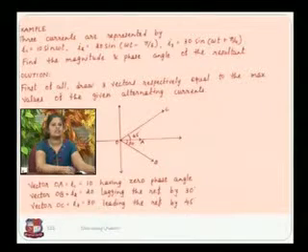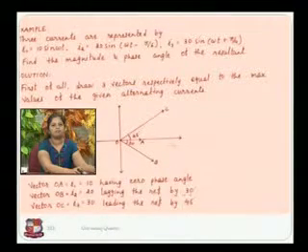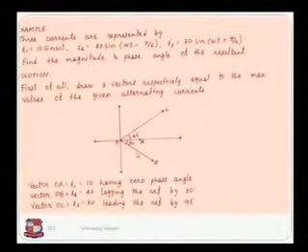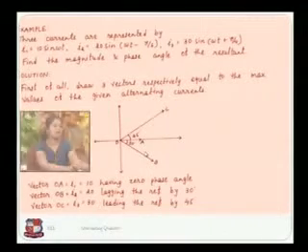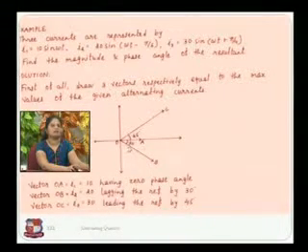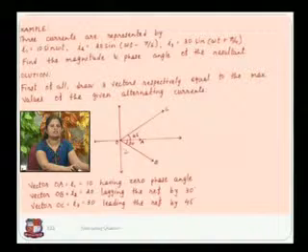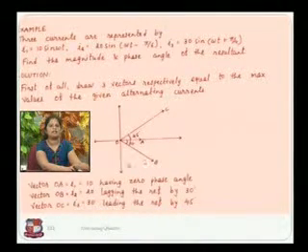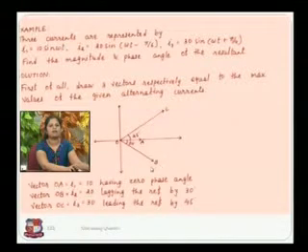So this is the vector representation of the given current. This is the first current OA, angle is equal to 0, magnitude is equal to 10, so here it is OA. For second current, angle is equal to minus pi by 6, so here it is 30 degree minus, so it is lagging, and magnitude of it is 20, so the magnitude of OB is equal to 20, angle is equal to minus 30.